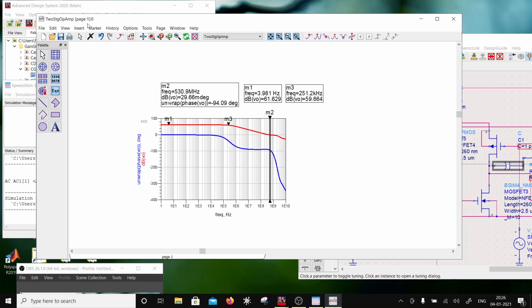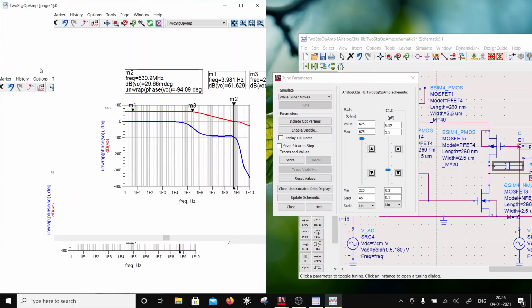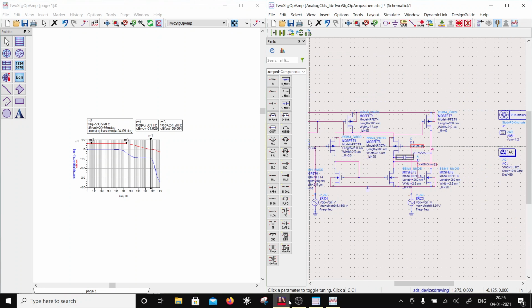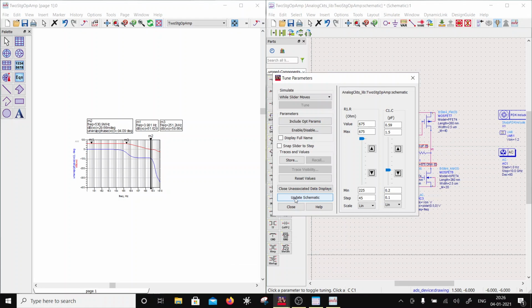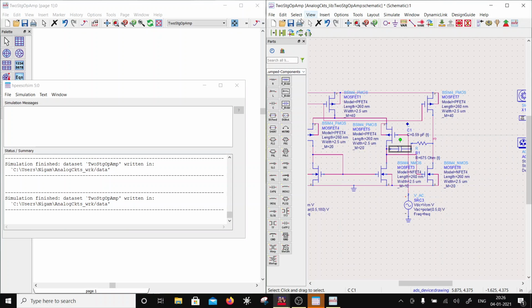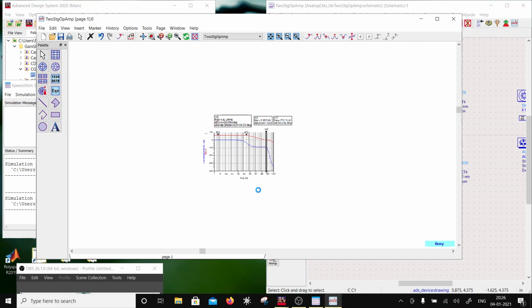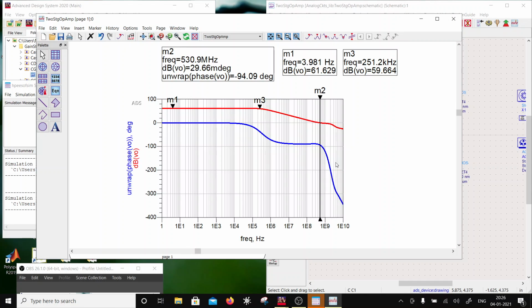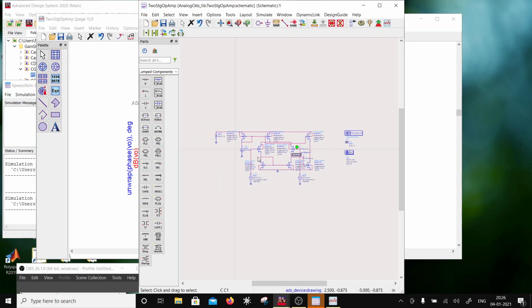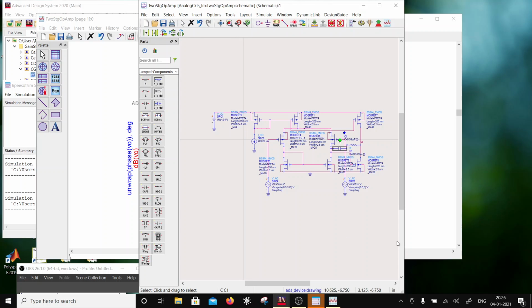So this is an example of an OpAmp design. So I'm just going to update. Just one second. Just going to update this and close this. Okay, so I'm done with the compensation part. Okay, and I have a result which looks like over here. I have an 86 margin, 61 dB gain, and corner frequency 250 kilohertz. So this can be used up to 250 kilohertz. So this is an OpAmp design example, and I am going to stop here.